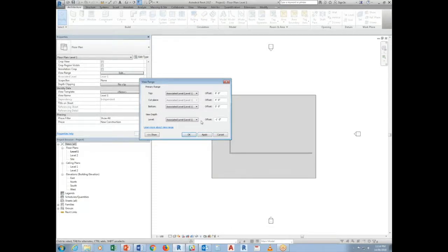Hey, is Simon? Yes. One thing I've just never comprehended is the difference between the bottom and the view depth. Yes, it's very confusing, but to keep it very straight, just make both of these numbers the same. I always do that because if you do that, you're not going to forget. Because view depth is what you want to see at the depth.